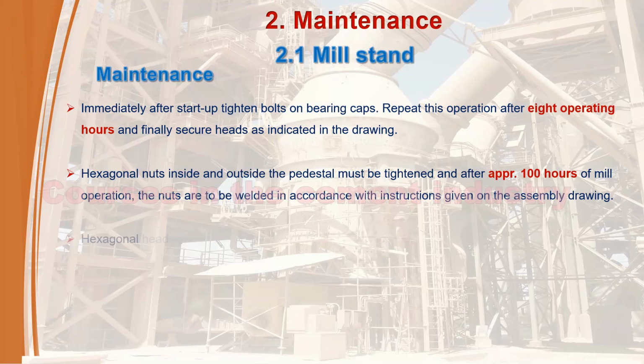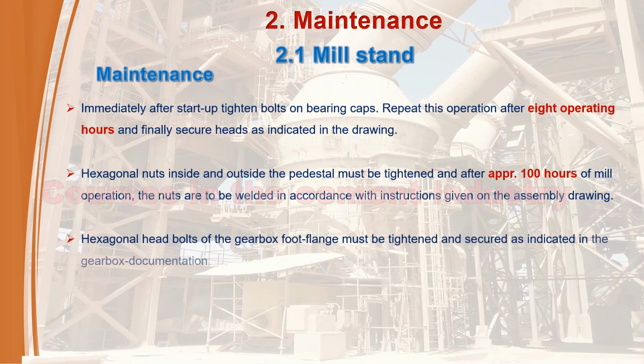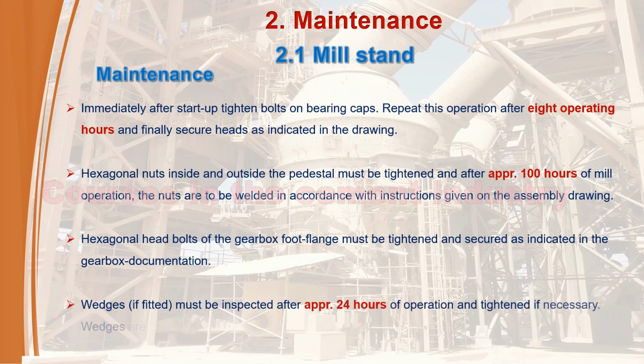3. Hexagonal head bolts of the gearbox foot flange must be tightened and secured as indicated in the gearbox documentation. 4. Wedges, if fitted, must be inspected after approximately 24 hours of operation, and tightened if necessary. Wedges are then tack welded lightly.